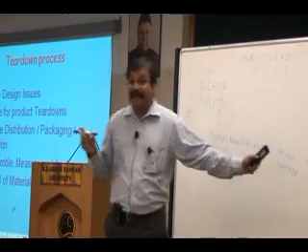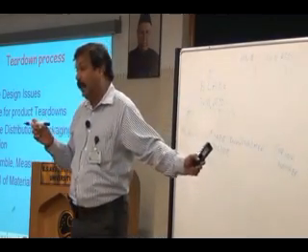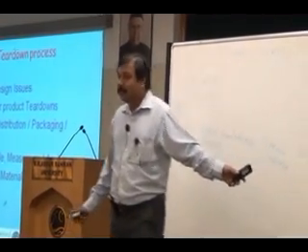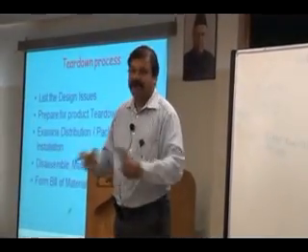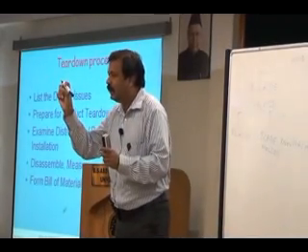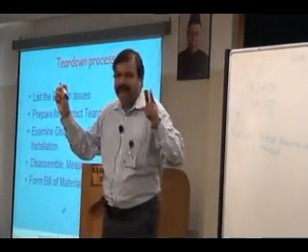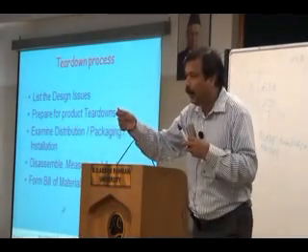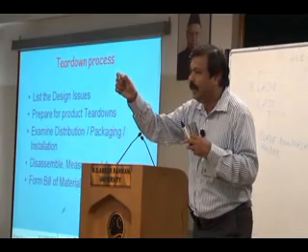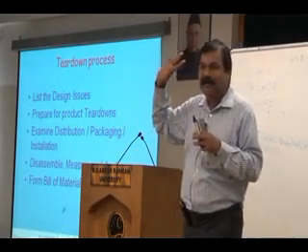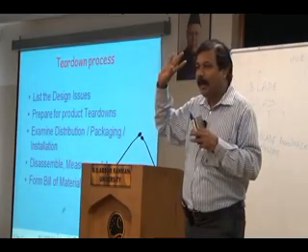All the skin of the aircraft is attached to the frame by means of riveting, because the frame is a thick material and the skin is going to be a very thin material. When you have uneven thickness, welding cannot be done. The moment you try to weld, the thinner thing will melt and flow away. You understand the difficulty?